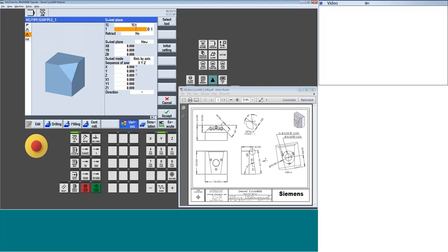I think where I would be more concerned is if I was on a machine where the rotation could affect the tool change, like a head-head machine, where if it's rotated and I tell it to do a tool change, I'm now relying on the machine builder to make sure they bring that head back before they allow it to tool change. So in a case like that, I may load the tool and then instate my rotation. So there might be a couple extra steps involved, or do it from this screen. In this case, since it's a trunnion and she's going straight up to do tool changes, this wouldn't hurt me, so I'm just going to leave it alone.